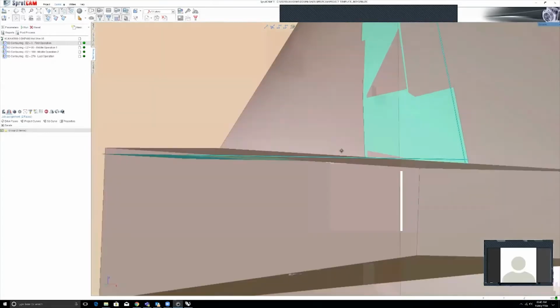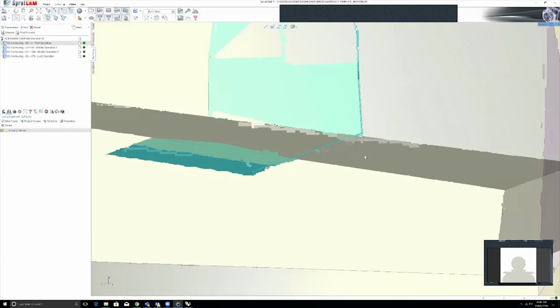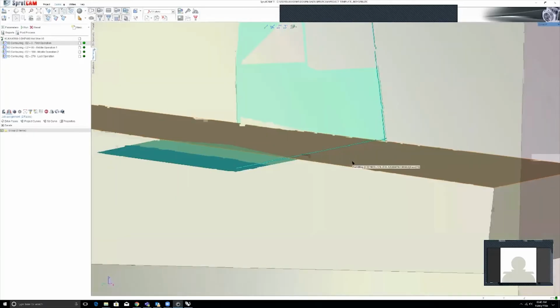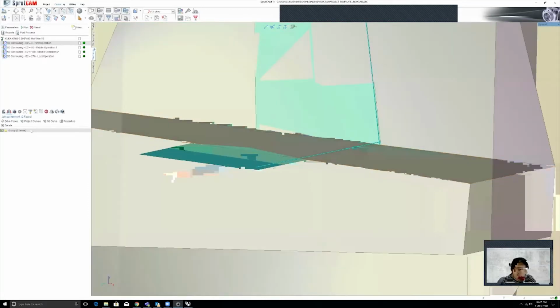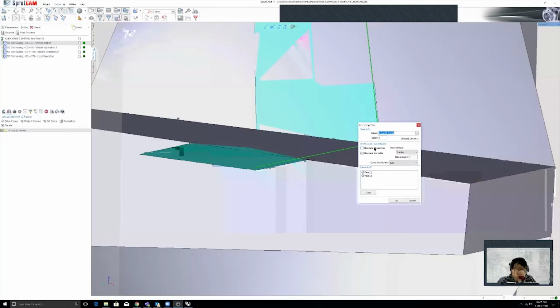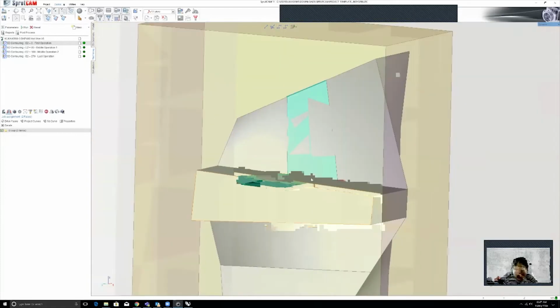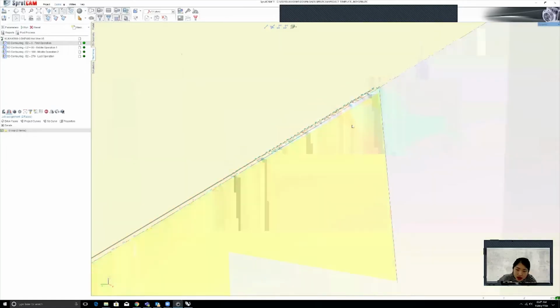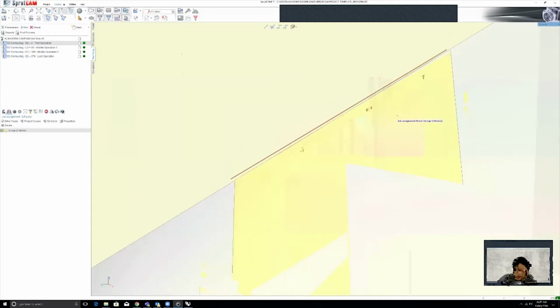I have a quick question in between. What was alternate streamlines again? Because when I used alternate streamlines, it did the same thing. Or is it something else than alternate face? Okay. So alternate streamlines actually means that it flips the U and V direction. So here we see that it's coming down and across, but if we check this one, it's appearing horizontally. And this orientation is not what we want, because you can imagine the wire cutting alongside this line, rather than following the profile of the surface. So that's why we should uncheck this one.